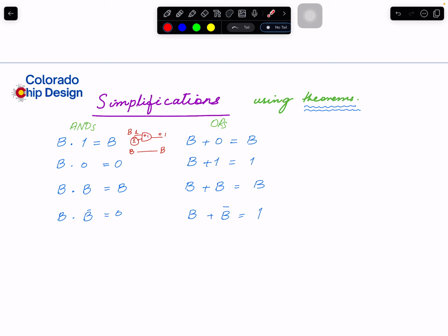There are transistors inside that are taking current, charging, discharging, which also creates power. And if it's in the circuit, it's also creating a delay. In that case, you don't need it. Simply replace it, just route this thing to the output. Similarly, look at this case. When this is B and you put 0 here, putting 0 here means the output will be 0. Doesn't matter what B is. So in that case, why are you wasting an AND gate? You simply ground that. Whatever that input is, you simply ground it because it will always be 0.